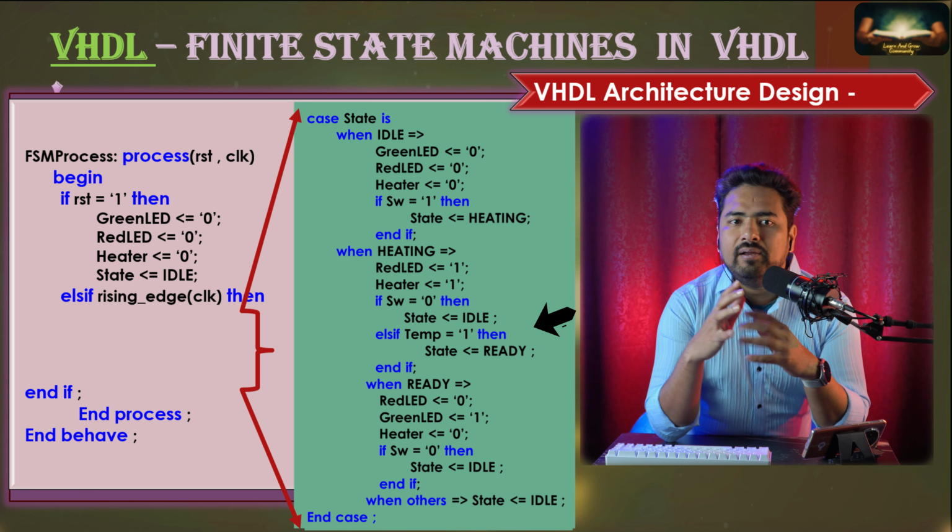But still, in real life or in actual hardware, there are many factors which can trigger these situations, because you can have a robust logic and error-free design, but you cannot control external issues like environmental issues or hardware failures. For example, hardware-related issues like power glitches, clock signal problems, timing violations, or power supply fluctuations. These may trigger some random state which may not be well defined in your system.